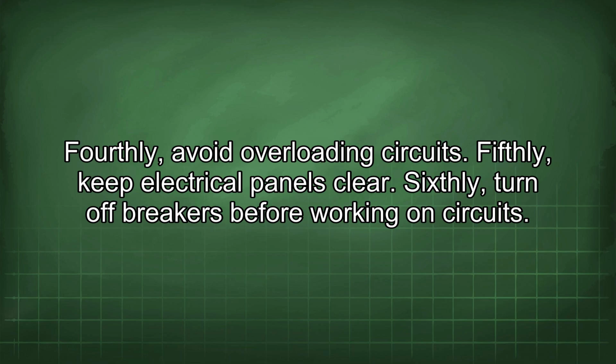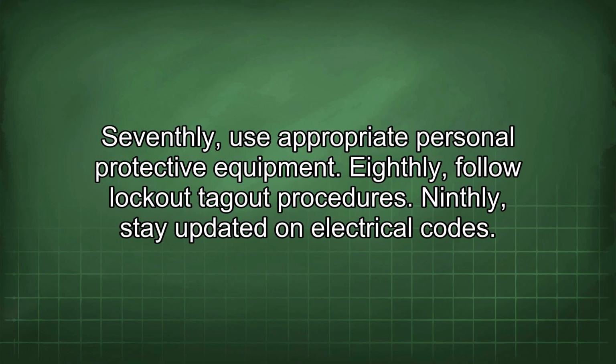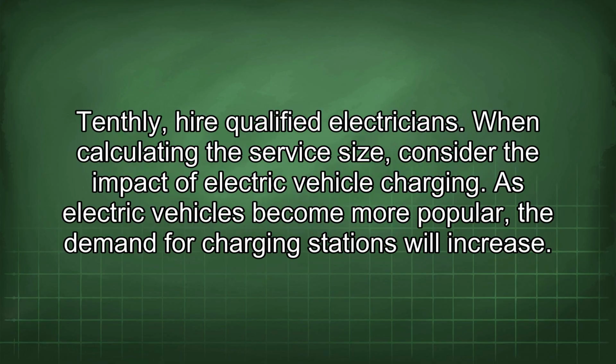Sixthly, turn off breakers before working on circuits. Seventhly, use appropriate personal protective equipment. Eighthly, follow lockout/tagout procedures. Ninthly, stay updated on electrical codes. Tenthly, hire qualified electricians. When calculating the service size, consider the impact of electric vehicle charging.